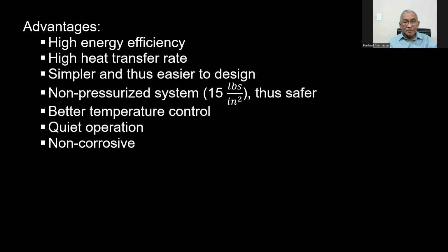There are several advantages of using heat transfer fluid over steam systems for heating. The first is high energy efficiency. Second is high heat transfer rate. Third is simpler and thus easier to design. And fourth is a non-pressurized system, well in the range of 15 pounds per square inch. Thus, it is a lot safer. Fifth will be better temperature control. Sixth will be quiet operation. And the seventh is non-corrosive.